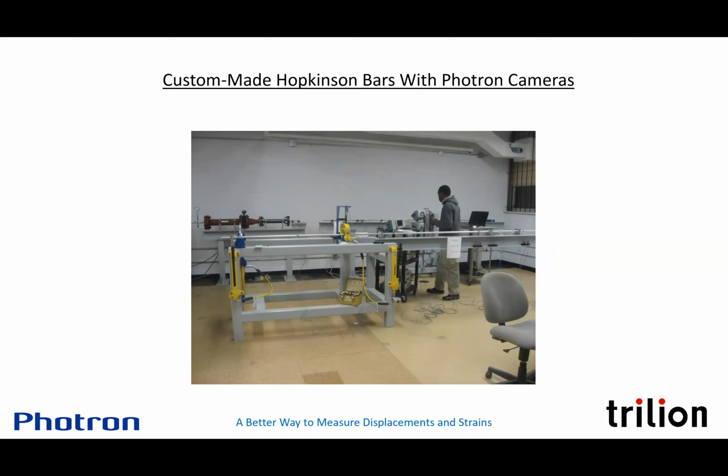These are Hopkinson bars that Trilion actually manufactured and delivered to Howard University. So when your high-rate MTS machine is not high-rate enough, the Hoppy bar is a very high-rate loading apparatus. We're doing 1,000 strain per second typically. So that's what Hoppy bars do. And you're seeing a custom camera mount here holding the pair of Photron cameras vertically to look at a 0.1 inch long compression specimen.